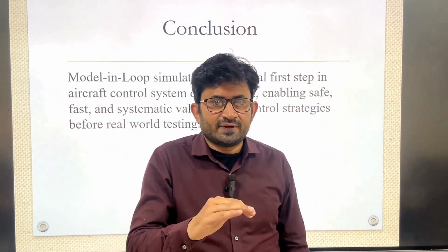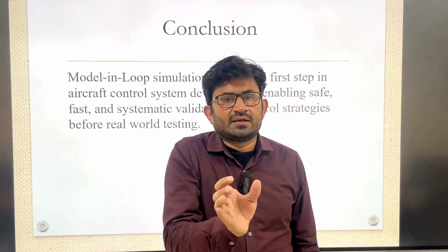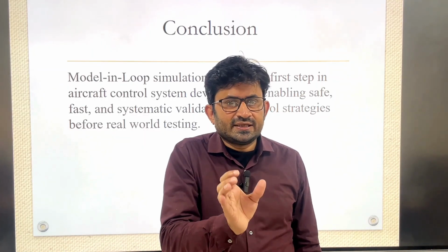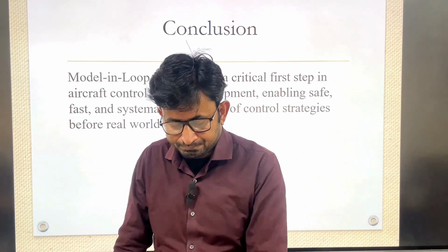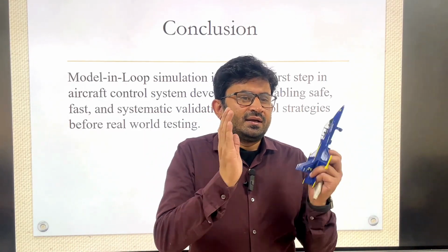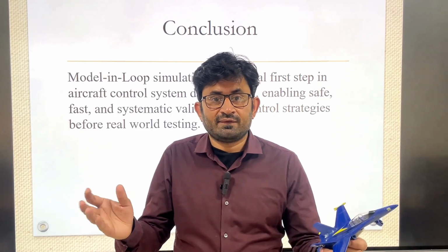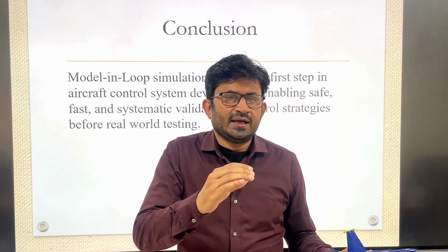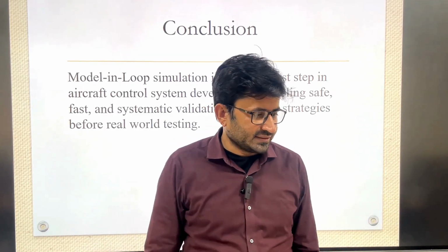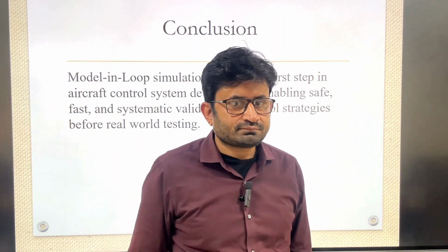Then once you are satisfied based on the standards, there is a standard in controller design, the MIL standard. If you are satisfied with those standards, then you can move towards software in the loop simulation, and then HIL simulation, and then finally flight testing, not on the full aircraft but a small scale model. And then once you are satisfied, you can go for a bigger size aircraft. Okay, so we'll continue from the next lecture.